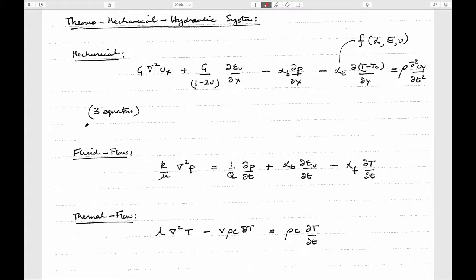is it takes, for instance, for hydromechanical problems, the solid mechanics part, and attempts to solve that in terms of the boundary conditions. And if you want to couple it to the fluid flow part, where these are the individual governing partial differential equations, what it does is it makes you put in a body force that accounts for the forces in the x direction and the y direction as a function of the fluid pressures.